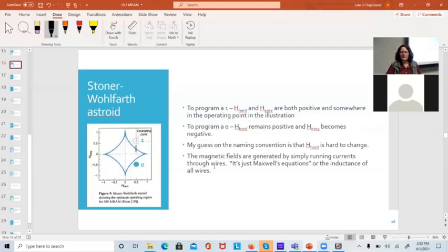And all wires have inductance. As we learned in 490, even tiny little wires, you can calculate the inductance of them. They're like in nanohenries or something like that. Little antennas hanging off of all your little DIP packages that you didn't even see. And this is why I groan when I see people with these loops of wire that are this long.